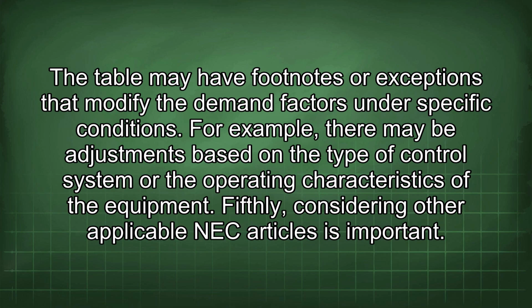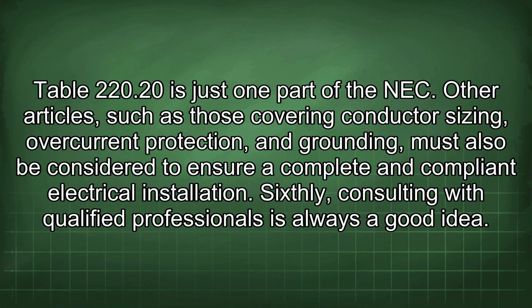Fifthly, considering other applicable NEC articles is important. Table 220.20 is just one part of the NEC. Other articles, such as those covering conductor sizing, overcurrent protection, and grounding, must also be considered to ensure a complete and compliant electrical installation.